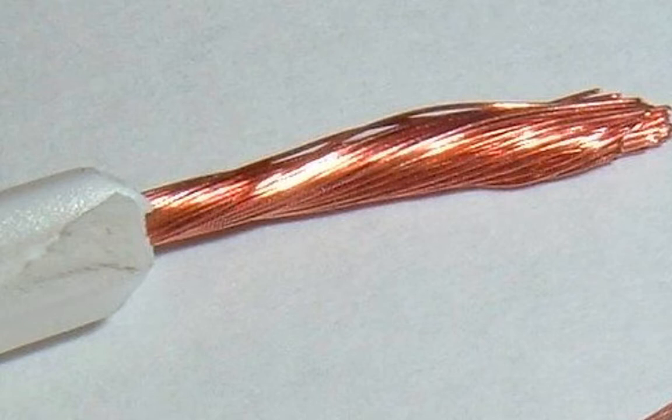And if it gets hotter than that repeated times and so on and so forth, plus there's a little bit of room in there for error because we like to be extra safe. They say that the code, the NEC, is actually safer than the international codes. So we have a little cushion in there for safety. And so we want to make sure that our wires don't heat up too much. If our wires did heat up too much, they could be a fire hazard. And remember, the NEC is published by the National Fire Protection Association, NFPA, and their whole deal is not about efficiency, it's about safety.